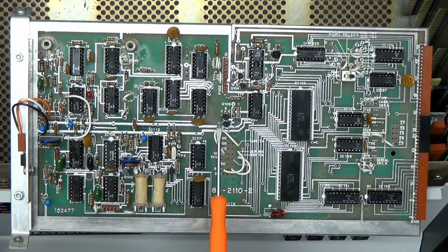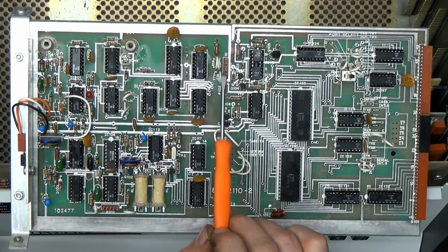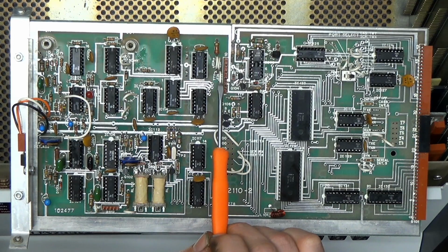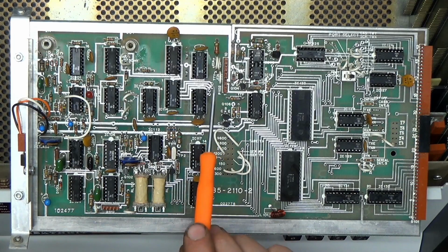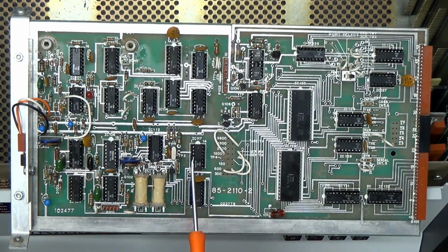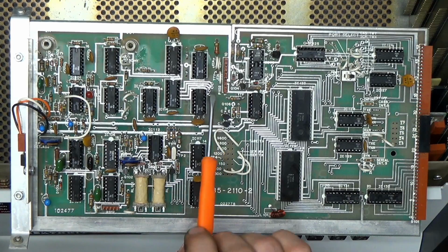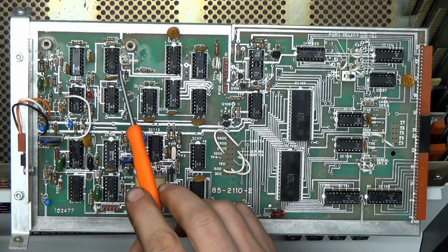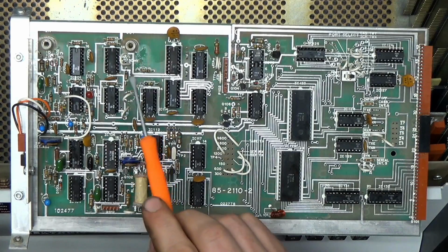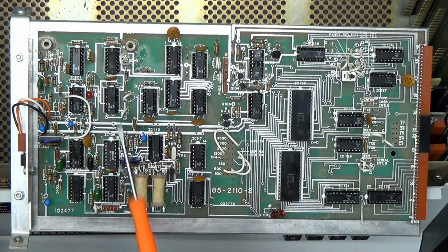It's got all kinds of funny stuff on it here. You can switch this header between TTY and EIA, which I assume means a 20 milliamp current loop, or RS-232 type signaling, although they didn't call it that yet. EIA in the old computer books generally means very much like RS-232. There's a bunch of stuff here. This looks like it must be for the gain of the output, whether it goes into a line level or a microphone level input.